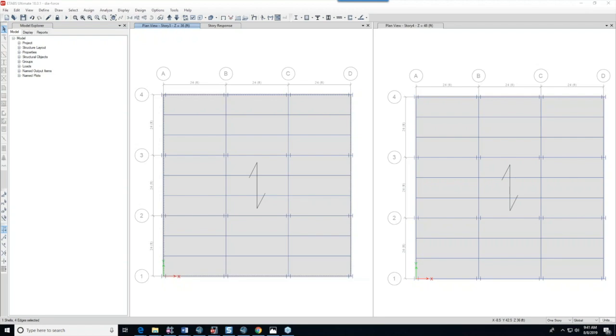It's really not intended to work that way in ETABS. But if you draw the sloping shells in there, the program will account for the stiffness of those shells, and you will get restraint or loads carrying from one floor to the other.